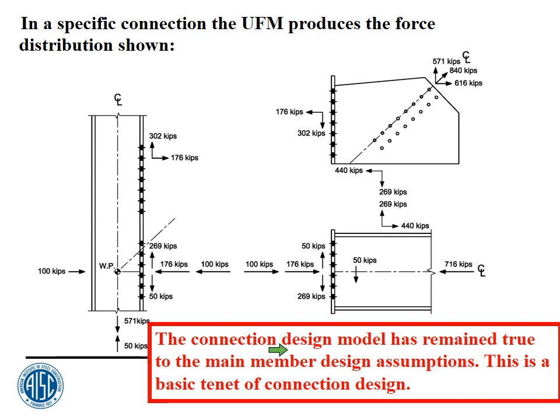I don't know the answer to that question. I know that for non-seismic, we have generally not done that. I do know that in seismic, this is a hot button item that some moment needs to be considered to make sure that you have ductility. But I think that particular issue is still up in the air. There are people working on exactly how this should be done, so I don't have a really definitive answer for that. For non-seismic, I have never considered a moment if it was considered to be a pin base. On seismic, I think the jury's out on that one at this point.